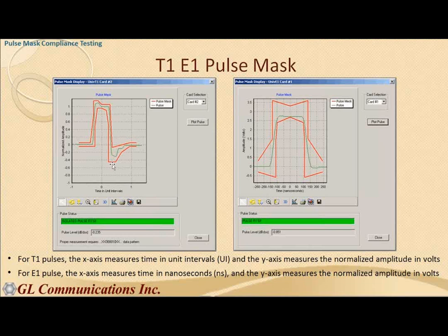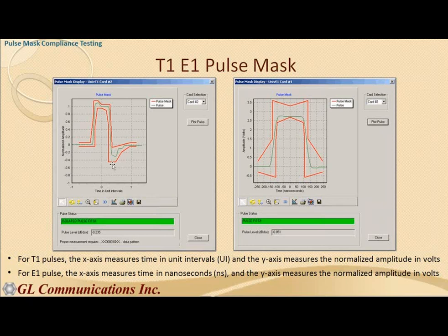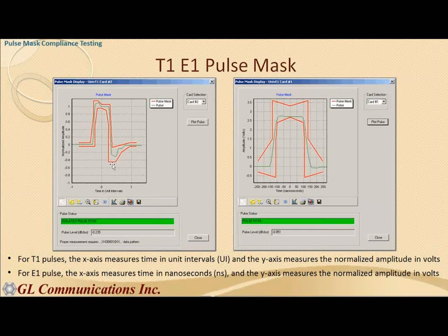Otherwise, if you send a 1 as a positive pulse and a 0 as no pulse, what will happen if you were just sending lots of zeros, which can happen, right? You would just send no pulses at all. Well, how does the other side know whether you're sending anything at all? No pulses versus zeros versus nothing.